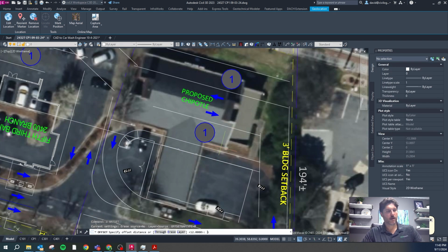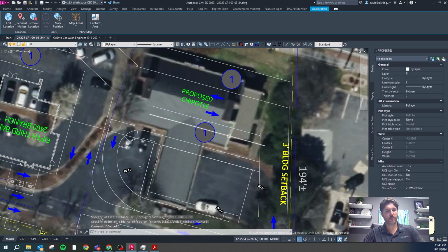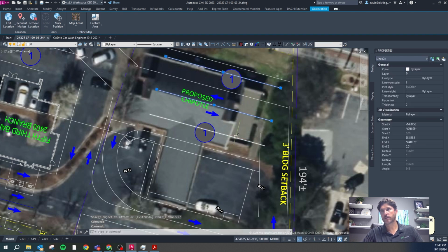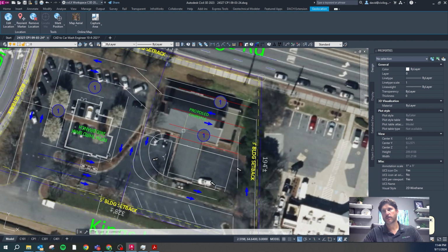Okay, if I did a 12-foot lane there, then people could go this way and pull in. Then we could really do an 18-foot parking here, and then a 24-foot drive aisle there. And so this system, and you might have seen this some places, where you park and then you actually have a crosswalk in between where cars are pulling up, and you walk between the cars and then go into the building. So that's a little weird, but it also lines up this drive aisle a little bit better.